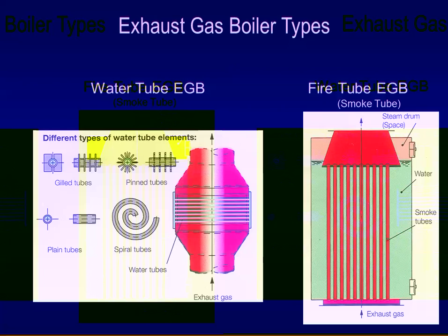With this, the one disadvantage is that, whereas with a water tube exhaust gas boiler you can blow tubes very effectively to clean it, these you cannot. So on occasion, you're going to have the extreme pleasure of crawling in underneath or above the exhaust gas boiler and running brushes down through the tubes to clean them. If you don't, you're subject to an exhaust gas boiler fire.